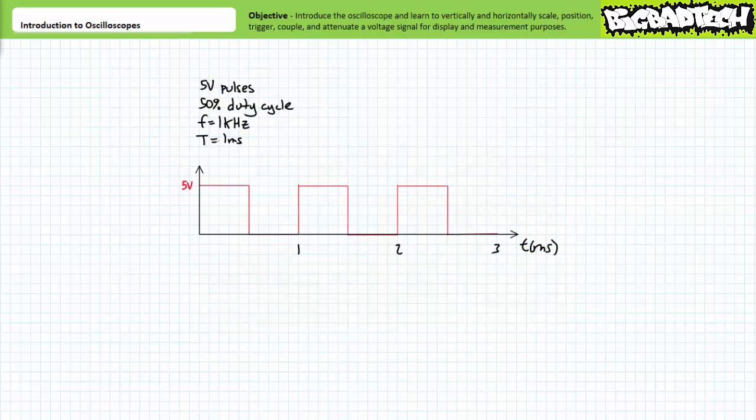Application of these features necessitates a bit of an example for purposes of comparison. Consider a pulsed DC waveform with the following characteristics. It consists of regular pulses of 5 volts and 0 volts entirely on the positive side of the voltage axis. Alternatively, one could view this as a pulsed AC waveform with a 5 volt peak-to-peak value going between positive 2.5 volts and negative 2.5 volts, including a positive 2.5 volt DC offset, thus shifting it entirely to the positive side, but this just complicates the issue. The easiest way to think of this for now is just alternating pulses of 5 volts and 0 volts.